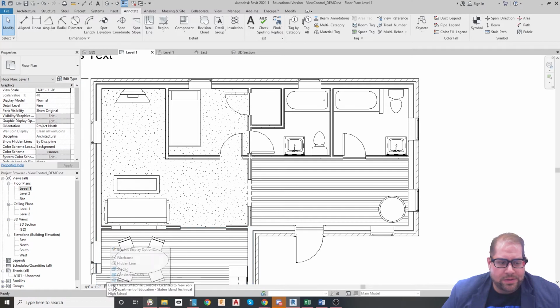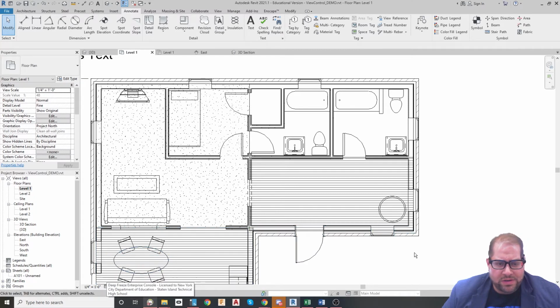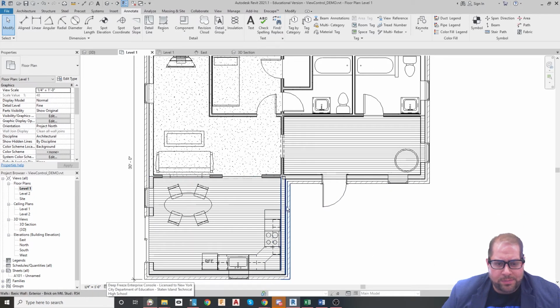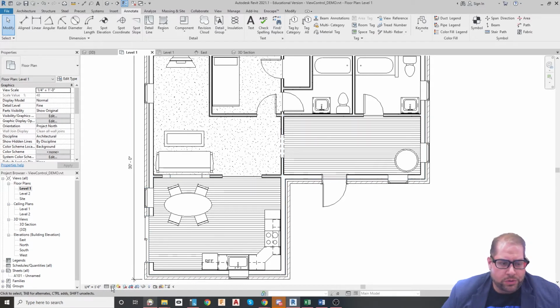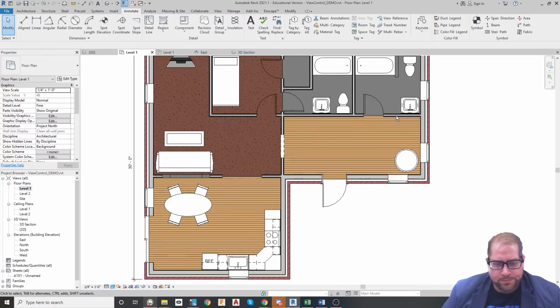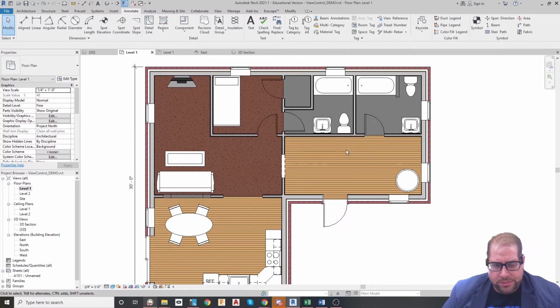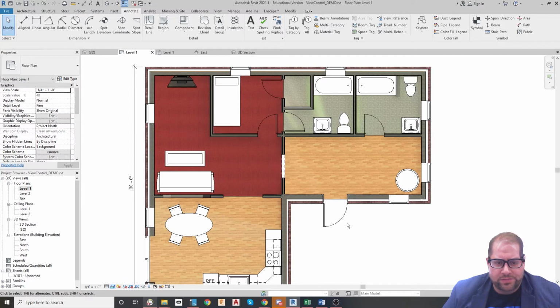As far as coloring, again, the wireframe view is like this. It shows a little bit more transparency and stuff. I don't think that's a good idea. We want to stick to either the hidden line view like this, or you can go to consistent colors, which is a really nice look for the particular 2D views. So either consistent color or hidden line. You don't really need the realistic view in this case.